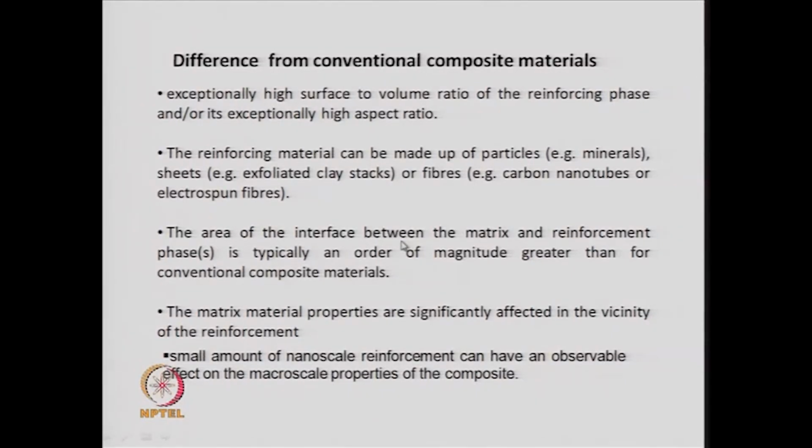So, the connectivity between the matrix and the added particles, which is being called the reinforcement phase, the area of the interface is an order higher in these nanocomposites compared to normal composites, which may have micron sized particles.